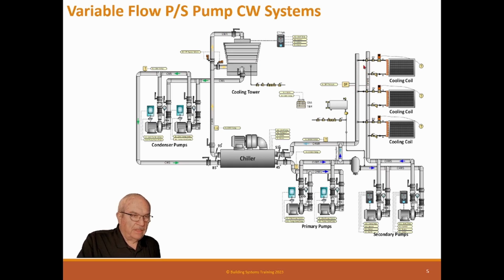with air. And when that happens, then when it restarts, the water comes up here, it's pushing a slug of air through the system, and it will probably mean plug flow. So this is why systems don't work well. And in the worst case, it can airlock a coil or airlock part of a piping system.